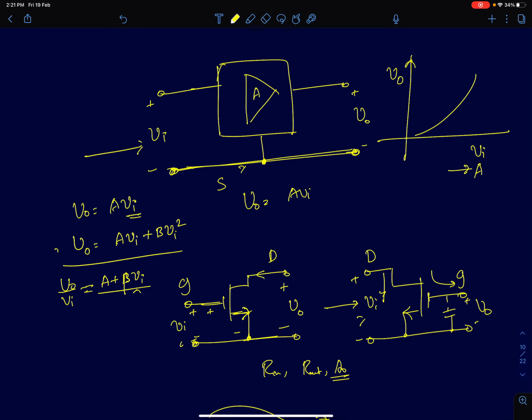What we do is something we have already discussed briefly. Now let's assume what I've shown here is a nonlinear characteristic between the input and output. We are going to assume that we are applying small signals at the input. At the input terminal, I'm going to apply a small signal around that input operating point or the bias point. We'll try to calculate the gain at that bias point and assume that that gain is going to remain constant for the small signals around that bias point.